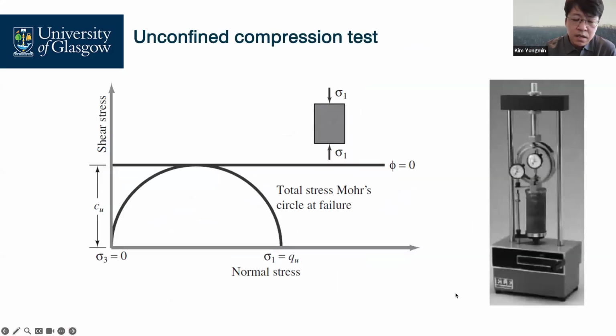This is not the triaxial test, just the unconfined compression test. Simply prepare your soil sample, put it on a certain loading frame and directly apply deviator stress. It looks similar to UU test results, but with confining pressure 0, just atmospheric confining pressure.